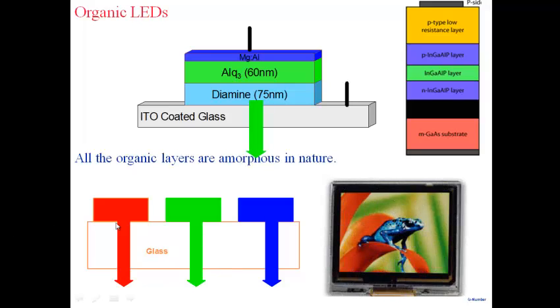And remember, the LED is being made on glass. It's not that I'm making it separately and then bringing it onto glass. No, I start with ITO coated glass, I deposit this material, I make this electrode. So the whole thing is being made on glass, right? Using masking and other ways, in one place I deposit these materials and get a red LED; in another place I deposit these materials and get green. Selectively, I make the deposition. And therefore, I'm making all these LEDs side by side. It's not that I'm bringing them and interconnecting them. The interconnects are also made on the glass. All right, so I can make this complete display on glass.